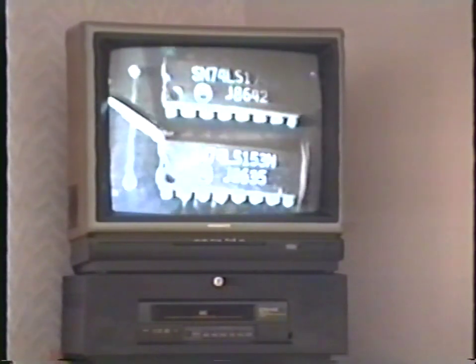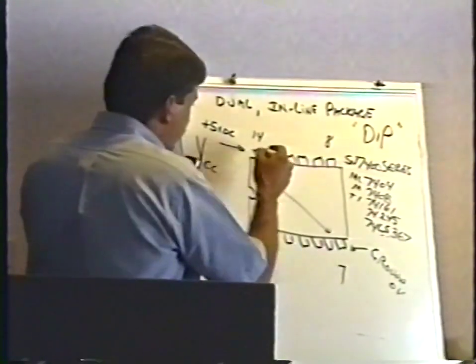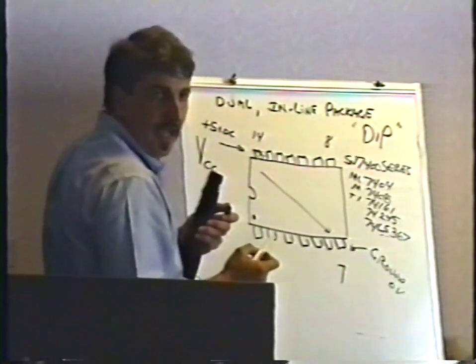See how I'm pressing on this? I'm not even looking at it now, and I'm holding it on there. I could never do that if I tried to put it just right on top of the pin. I'd have to be very careful to not short the two together and slip. So by putting it in the corner like that, you can jam it up in the corner, and it won't slip off. So make sure you do that because the power is turned on, and if you try to put the meter probe right on the top of the pin, you'll slip and short the two together.